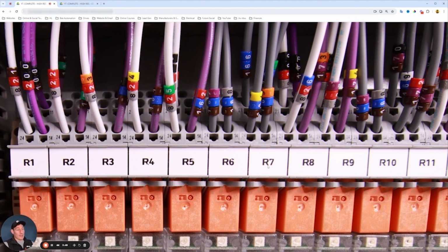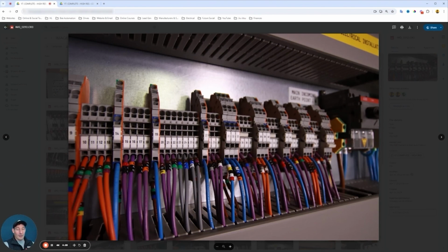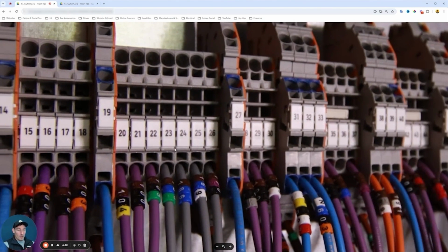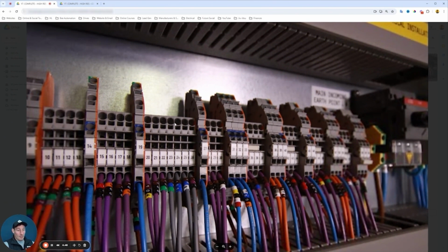And because that relay is now energized, that's allowing those feed cables to then feed through the contact and out on 166. And you can't see this one, but this is 165. And then those terminals go off to the terminal blocks. And those terminal blocks are 23 and 24, which you can see here. So 116 and 165. And then we'll have our field cables connecting in here and going off to the boiler.